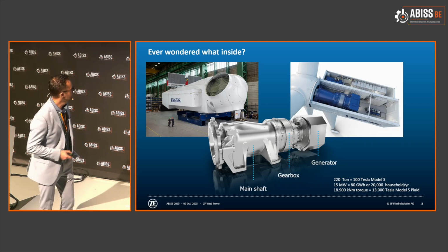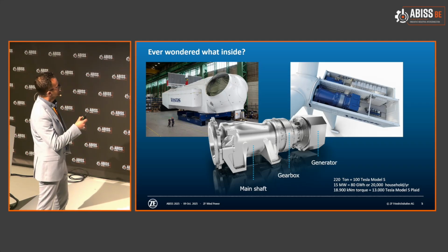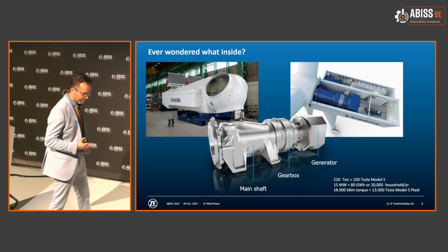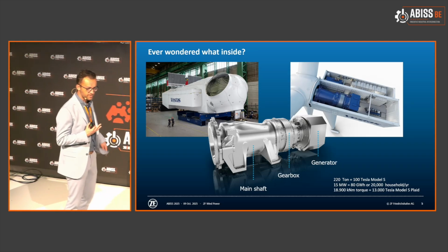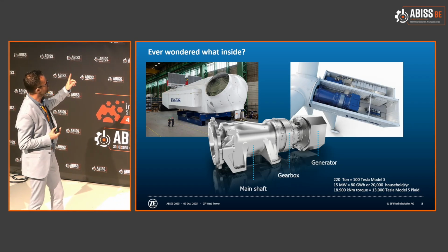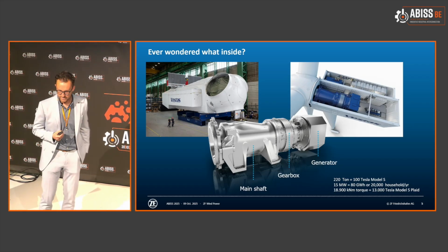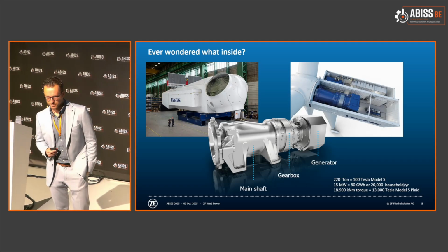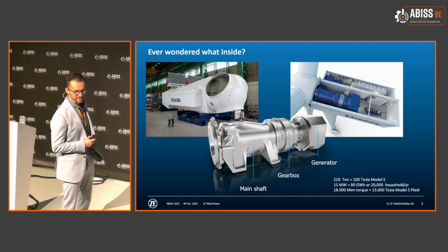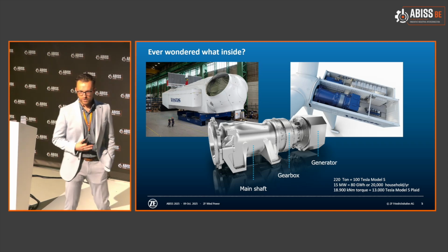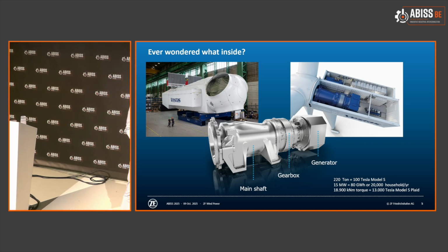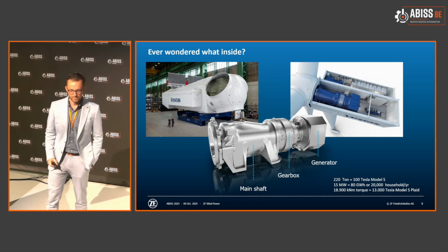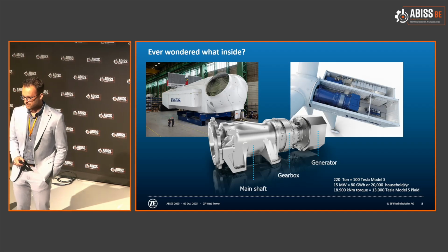And what we produce now is not just the gearbox, but it's an integrated powertrain, meaning those three elements that I talked about in the beginning are now combined into one product, and one product is about 220 tons. Yeah? To put that in perspective, around 100 Tesla Model S's. Now, I mentioned torque, big torques, high forces of the rotor blades. Well, this baby can take up to 18,000 kilonewton meters.